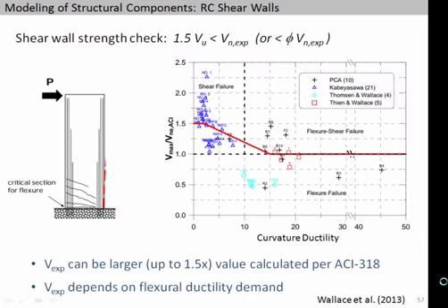Another thing: we talked about the walls being shear controlled, that is, modeling the shear in the wall as elastic. So the shear checks are kind of a strength-controlled check on the walls. Typically we'll take 1.5 VU, VU being the mean value, and compare that to the expected strength of the wall. That's if you're in LA. If you're here in San Francisco, it's 0.75, because we put the phi factor in there on the expected strength. And Farzad said it's just 0.75, but when you're talking to an architect and this is driving the thickness of your wall, that 0.75 is a big number.